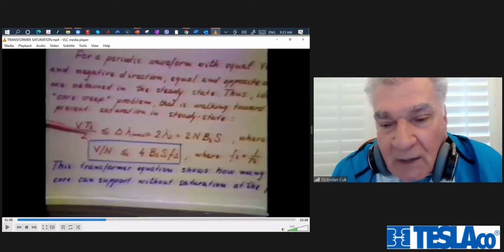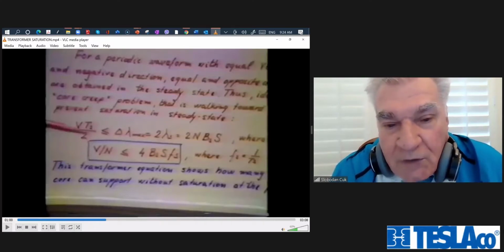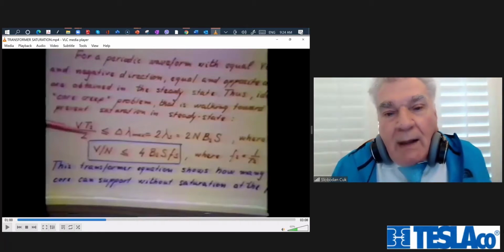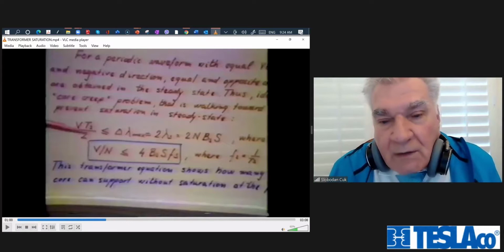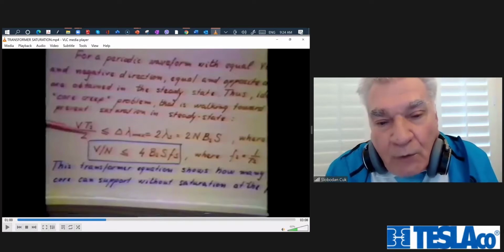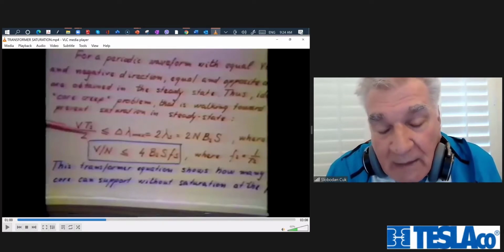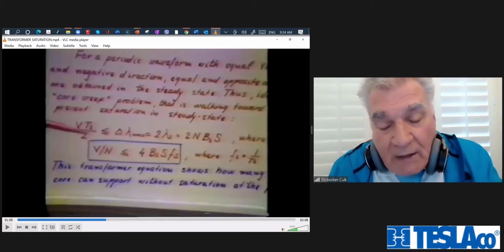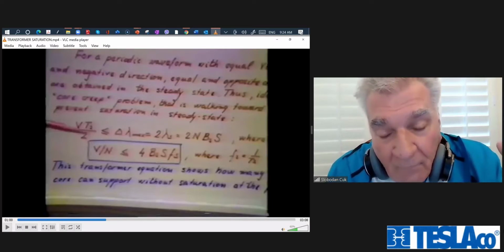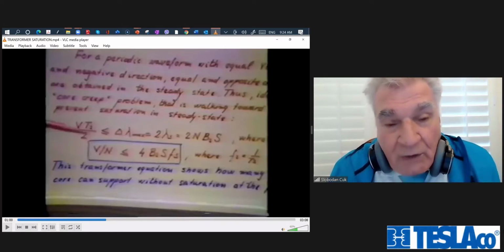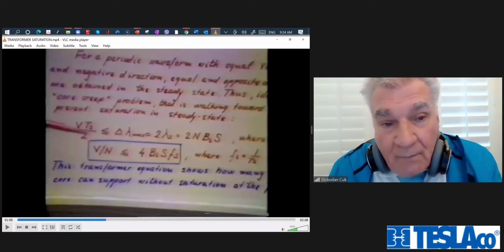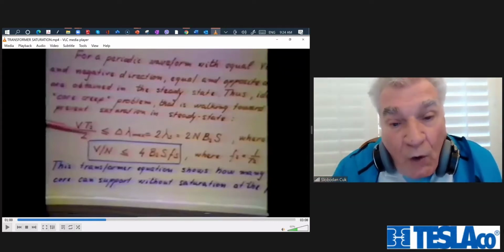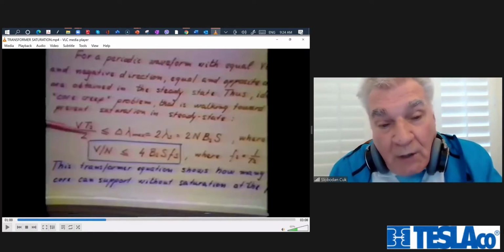It went in a direction that is not following what you have to do to make magnetics in switching converters that will follow the rules that were set up, except we cannot do what Faraday or Tesla did, that automatically, when he had a sine wave driven voltage source, you have positive and negative flux, which are automatically volt-second balanced or flux balanced. So there is no problem of driving the core into saturation, as long as the magnitude of that is, for a given frequency, proportional to the core size.